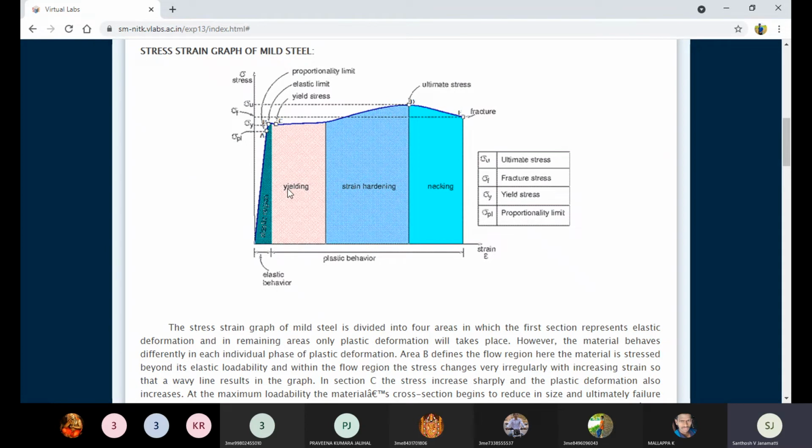That is up to a certain period of time. Up to the elastic limit, we will get a straight line. Now you can apply the slope to the straight line, right? Once you apply the slope, you can take those values. With the help of the slope, we need to determine the Young's modulus of the given sample. Why do we need to find the Young's modulus? Because we need to know the stiffness of that particular material.